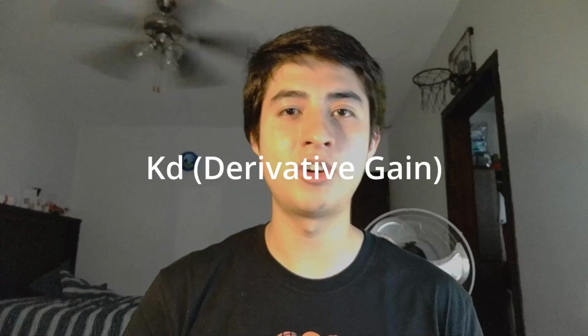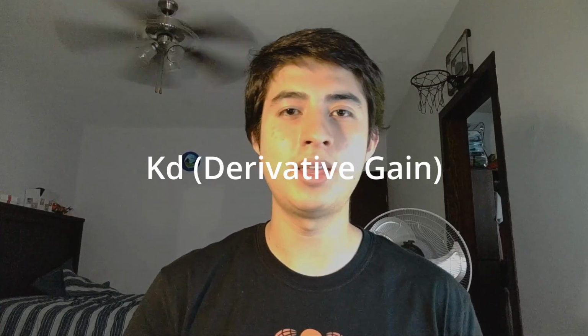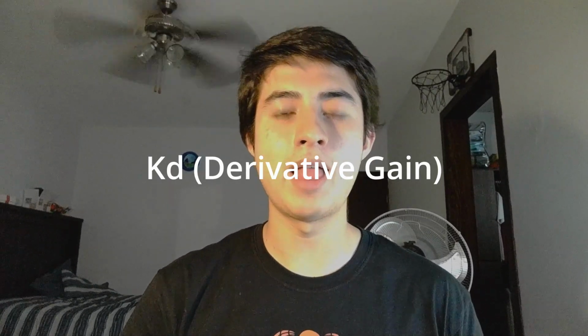Then we have the derivative gain. Basically, it controls the derivative part and allows you to prevent oscillations and also overshoot. But be careful, because if you increase KD a lot, you will have more oscillation and more sensitivity to noise. But if you have a lower derivative gain, you will have a lot of oscillation. So as I said before, you need to find a sweet spot to start playing.